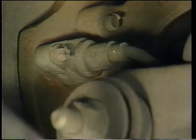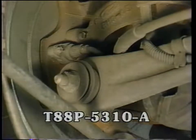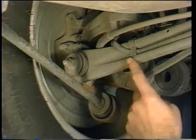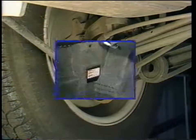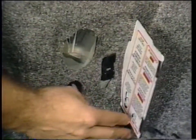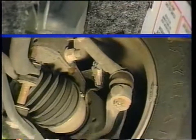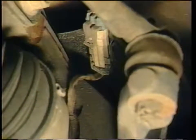Some vehicles, like the Lincoln Continental, need a special tool, T88P-5310-A, to lower the suspension arm to remove the rear sensor. Be sure to check the appropriate service manual. If the vehicle is equipped with an air suspension system, be sure to deactivate it before the vehicle's wheels are lifted off the ground. There will usually be an on-off switch in the trunk for this purpose. All wheel speed sensors on GM vehicles with Teves Mark IV systems are not adjustable.